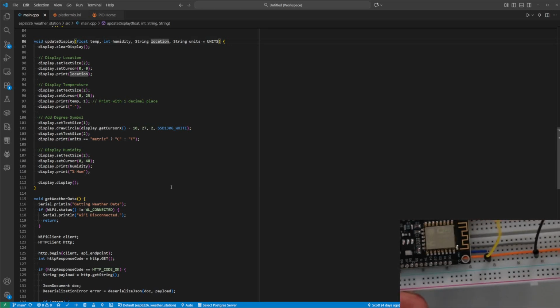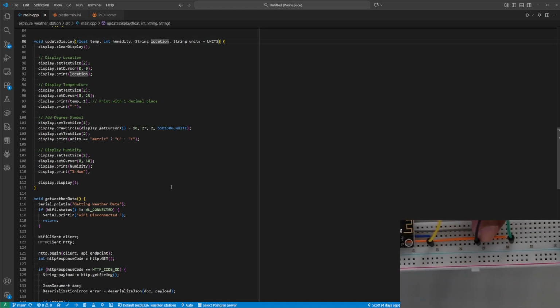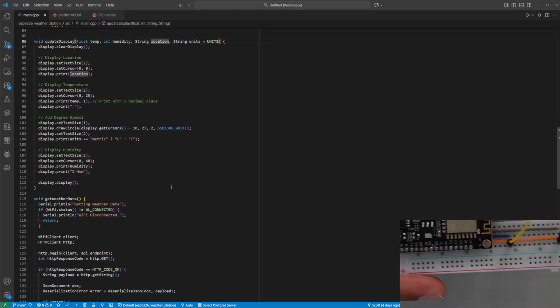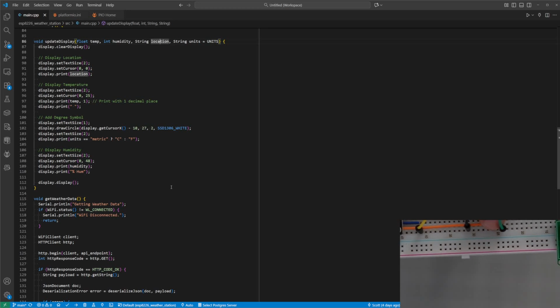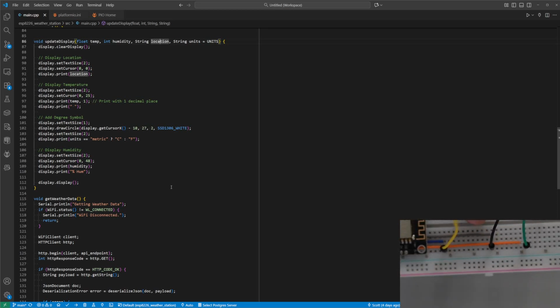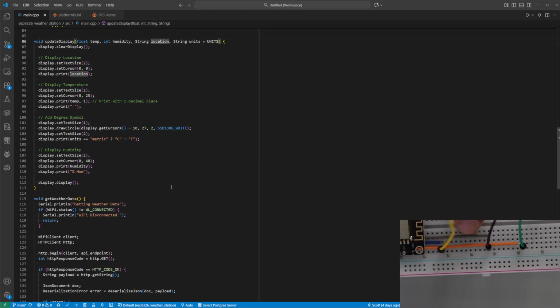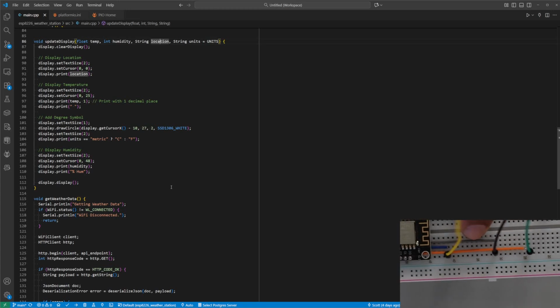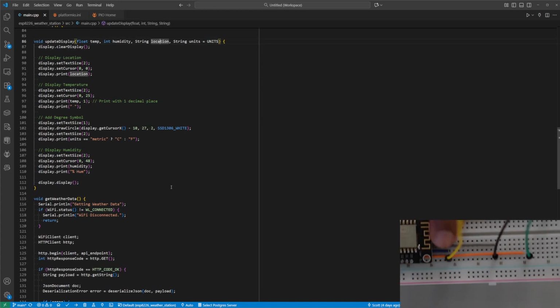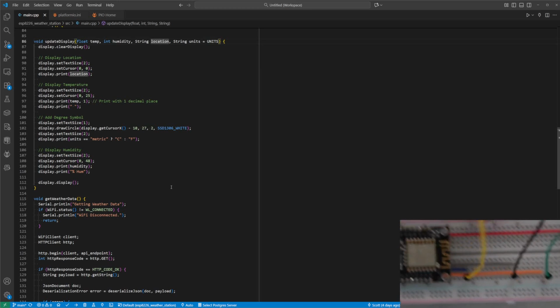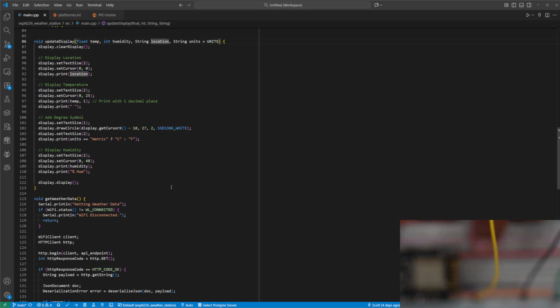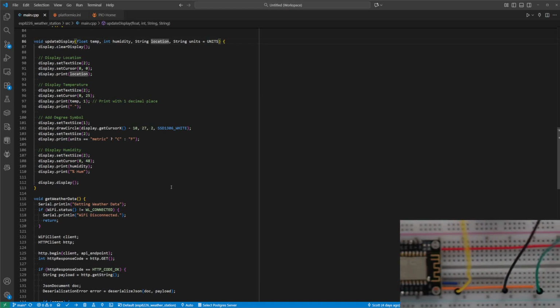So all that we have here is this orange is running from the ground pin on the 8266, which is kind of hard to see here. But this is going to be ground, the orange, and then I have a gray here that's running from D1, which is the clock line, and the blue here is running to D2, which is the data line. And then just up here on the red line, this is the 3.3 volts.